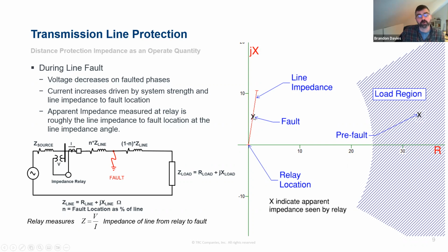Yeah, so most faults on the transmission system will have some arc impedance, but it's not going to be a highly resistive fault. Utilities don't let trees grow near their transmission lines. They've got big programs to make sure that doesn't happen, and they maintain the right clearances because they don't want to have faults on their system. So resistive fault coverage is maybe a little bit less of a concern at the transmission level because there are more controls on it than on a distribution line next to the road, where a tree could fall right on it.